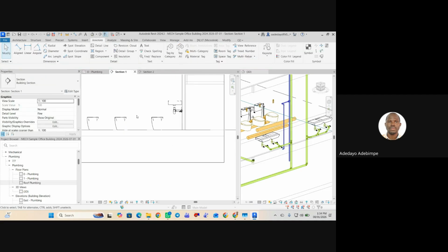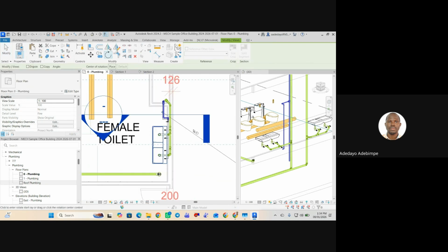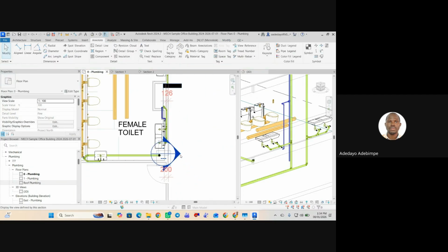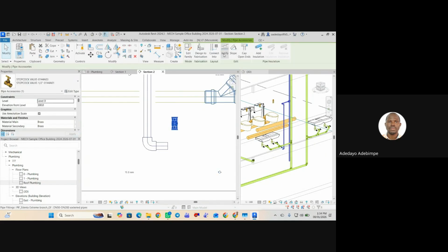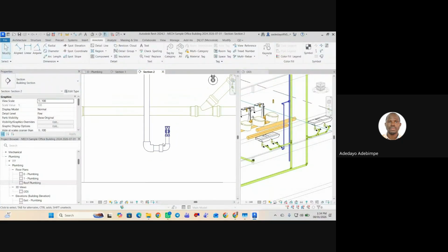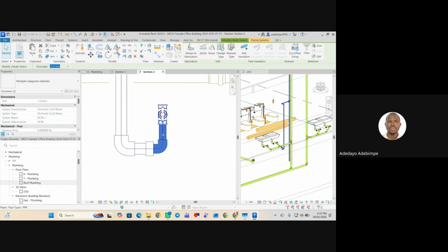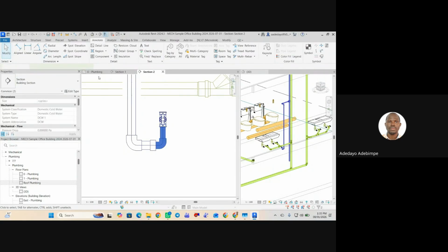So we need to connect into our stopcock. I need a section that speaks to that. Let me use this 90. So I can just click this guy and say connect into. I want, yes, the lower side. Okay. So you can see that this stopcock I have used is small, but I'll just proceed with it either ways. So let me change this to 25.